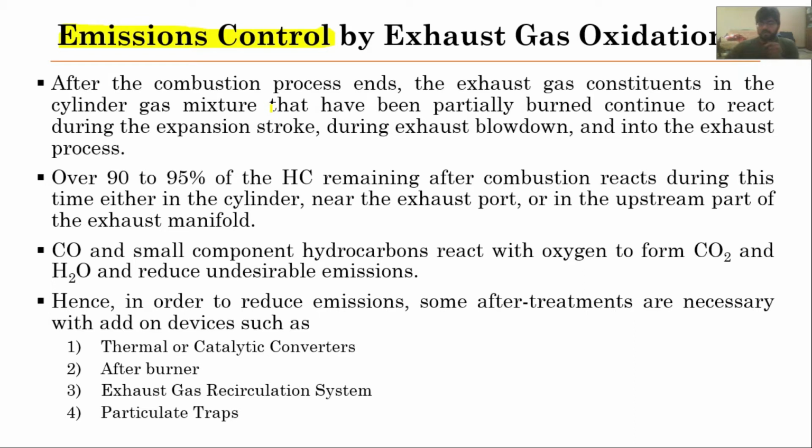So as I mentioned earlier, after the combustion process ends, the exhaust gas, which constitutes the cylinder gas mixture that has been partially burned, continues to react during the expansion stroke, during exhaust blowdown, and into the exhaust process as well. Sometimes the reaction doesn't completely occur, therefore during the exhaust process and during the power stroke as well, reactions are still going on.